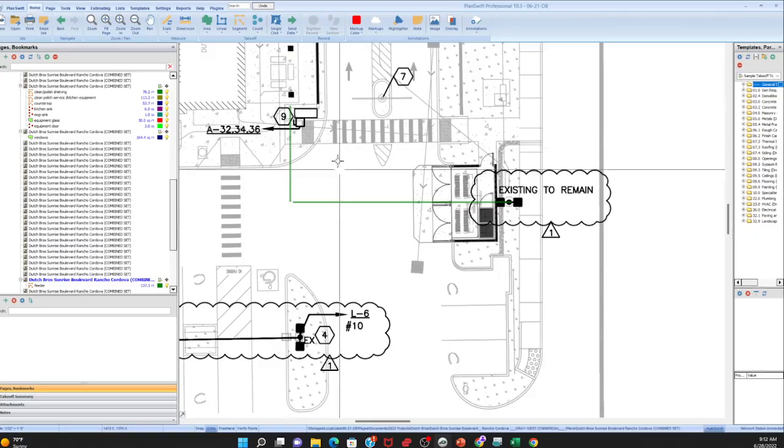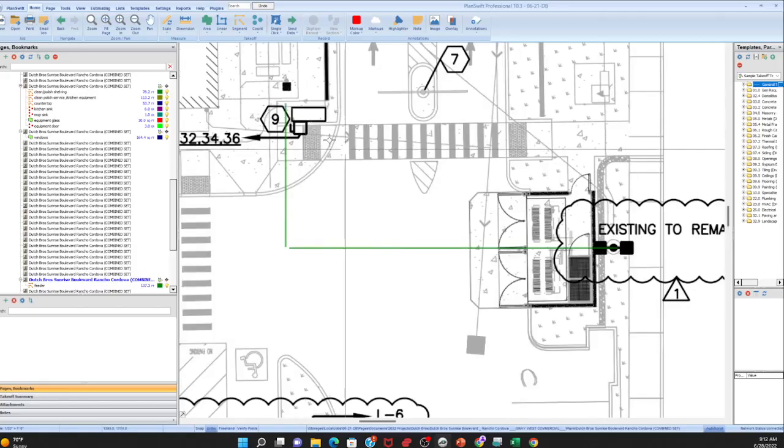So what you can do is all of this is PVC, and then you can allow another 10, 15 feet for EMT or rigid steel because you know it's going to come up. And so when it comes up to the feeder, let's try to find the single line diagram now.